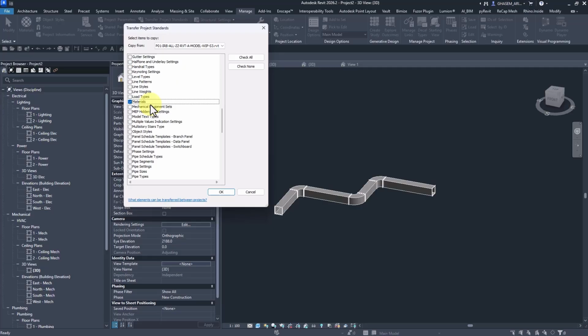By problematic materials, guys, I mean, for example, the ones that contain empty fields. Like, the fields should actually have a value to them, but they are empty. In previous versions, such materials would have been transferred inside our current file as well, and this could have created more problems. Like, the file would have become quite heavy, or it would have just crashed. But now, we have quite a detectable stability.